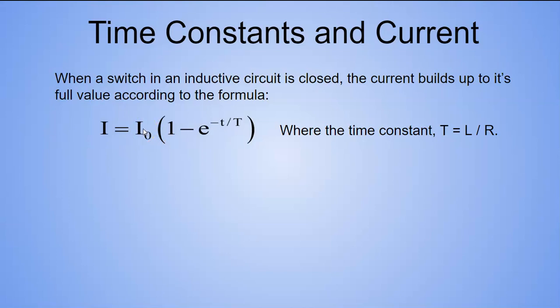When that circuit is closed and the current begins to go through, it will get to the inductor and start through the inductor, but now it's going through a coil. So that's a current in a magnetic field. It will generate a magnetic field from that current, but that changing magnetic field in the coil will self-induce a back current and cancel some of that out. So it's going to creep up like the capacitor charged. It's going to have that same kind of exponential growth to a maximum that you see right there.